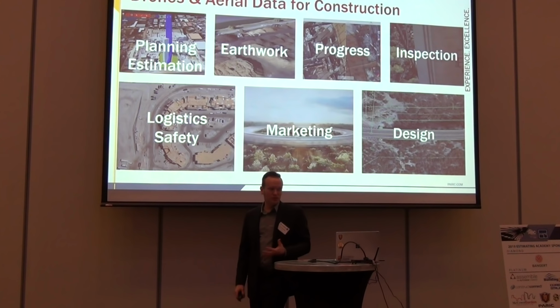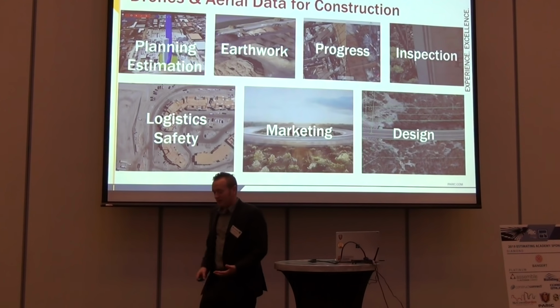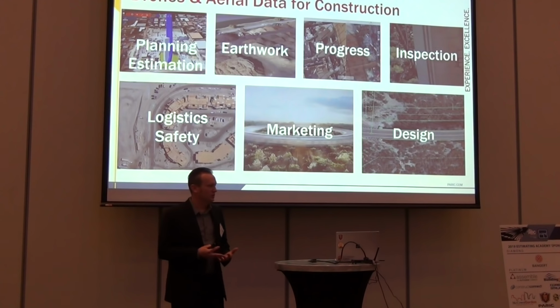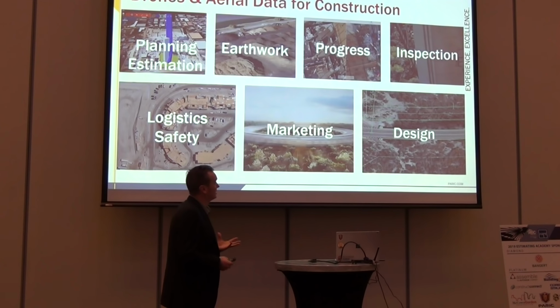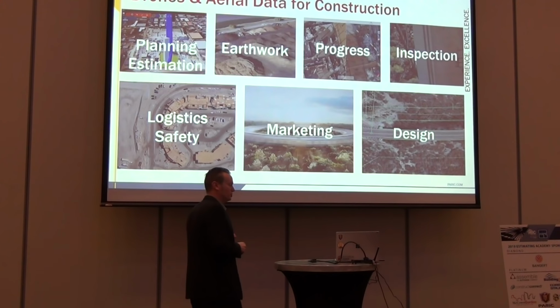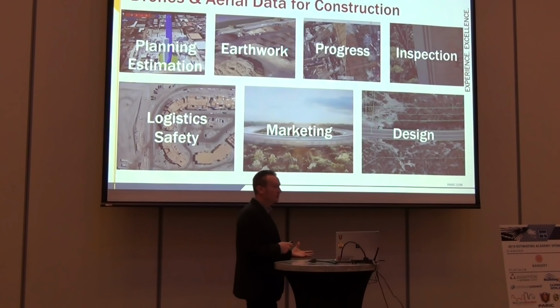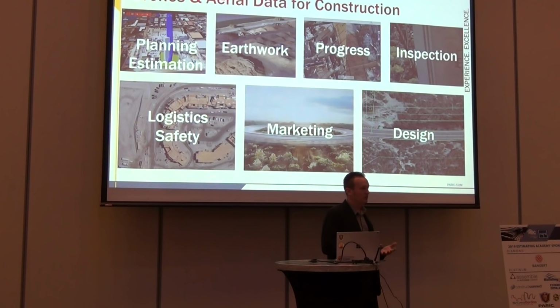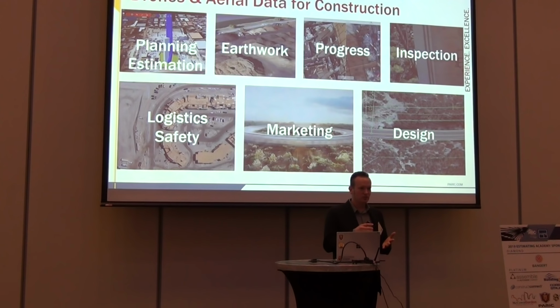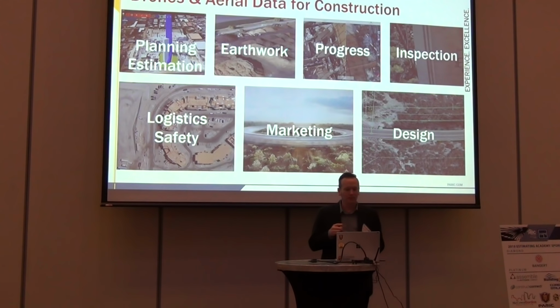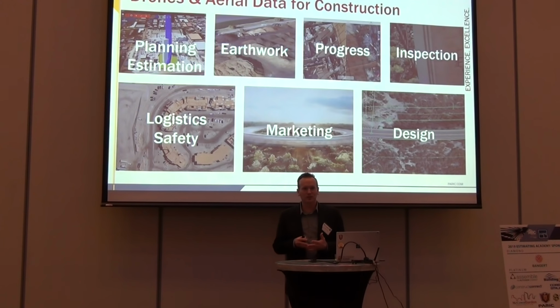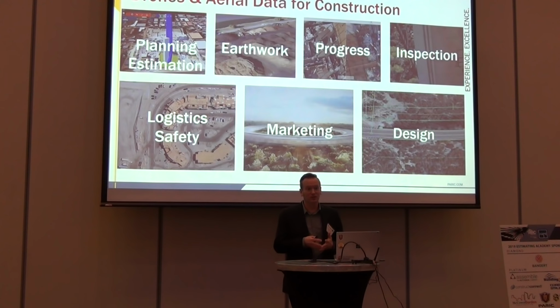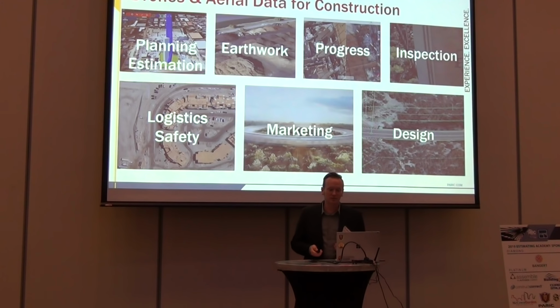So what can you do with drones? Obviously, it impacts how you plan your logistics. We talked about that a second ago. It impacts your design. It allows you to market your services and your progress, the way that you're going from day to day, whether it's steel erection or earthwork. Just knowing how many cars were parked on the job site, knowing before you start design how many cars are actually parked in the parking lot, so you can go back to the city and ask for that variance. There's all kinds of use cases.